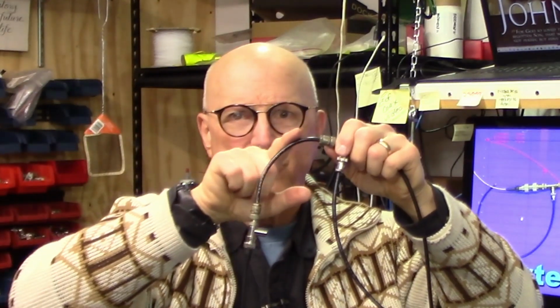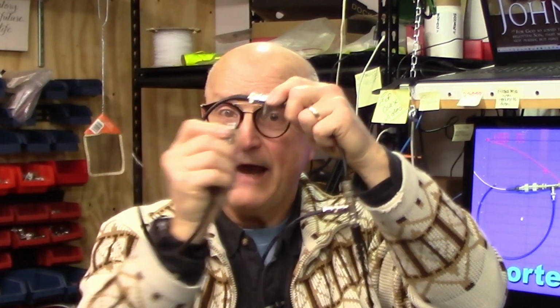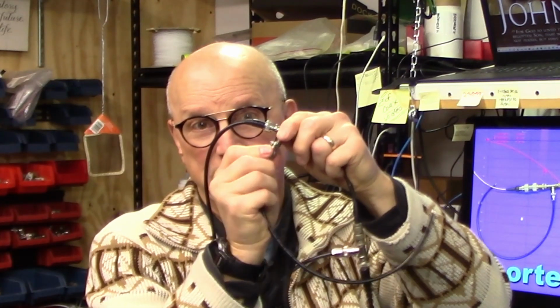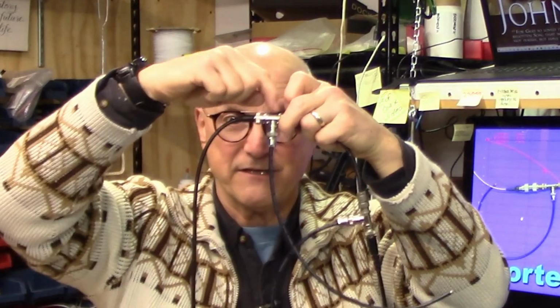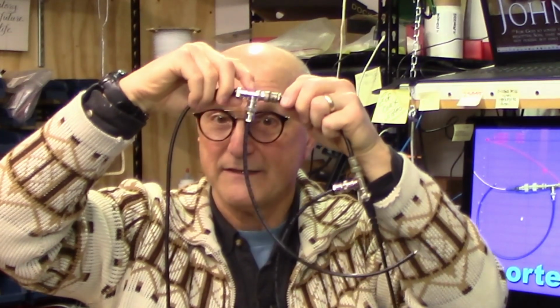We're starting out with a very low impedance at the first T, and going through the impedance transformation of the 1/4 wavelength, we are presenting a high impedance at the next T. We now connect another shorted stub, which is 1/2 wavelength long at the frequency in question, at this second T. Now, because it's 1/2 wavelength long and it is shorted at the far end, it presents a very low impedance at the second T at the frequency in question.